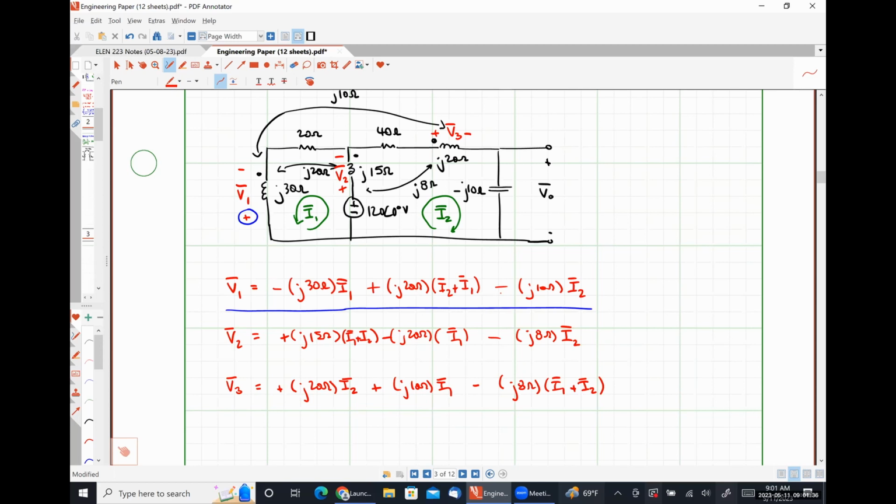Yes. It's the voltage on the first coil. Exactly right. That's the most confusing part. We're just looking for the voltage polarity on coil 1, and then how the current is behaving for coil 2 or coil 3, in this case, in a 3-coil system. Absolutely right. So all of these signs are depending on the voltage for coil 1. And then the self term is the current for coil 1. The first mutual term is the current for coil 2. The second mutual term is the current for coil 3.